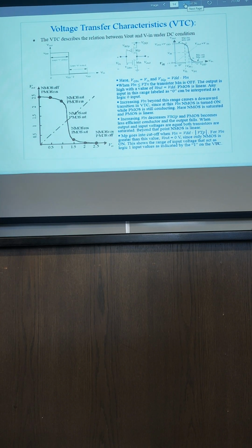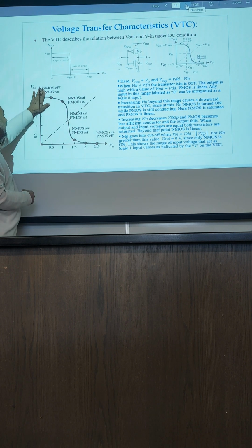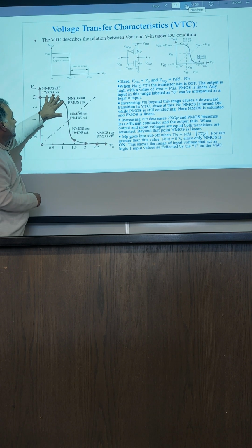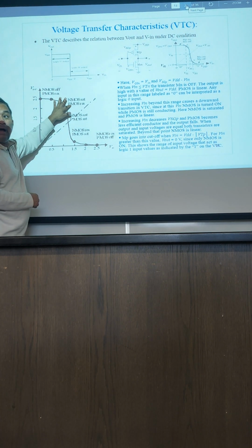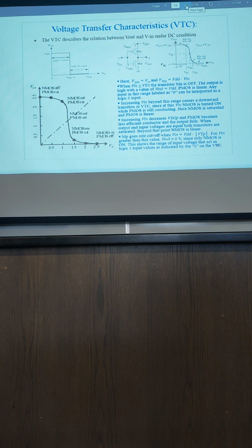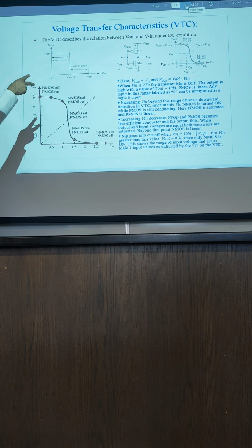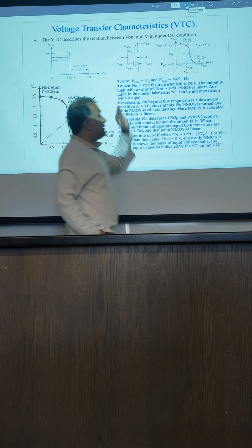So now the question is, I'm just saying that here NMOS is off, PMOS is on, here one is in saturation, one is in linear. I want you to write down all the linear and saturation conditions for each of the 2 transistors in this inverter and check the conditions by yourself to make your concept clear. For each individual transistor, you have to test that.